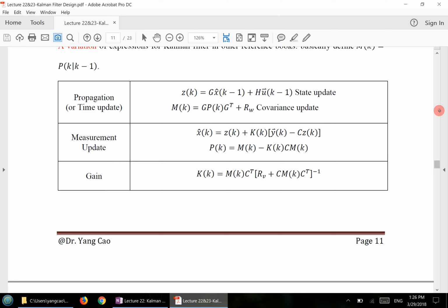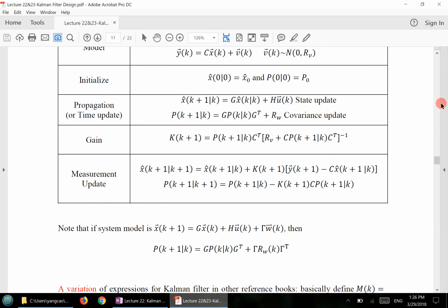So now you come to the Kalman filter design here. You have a gain here, and you have a difference: this is the sensor output minus that Kalman filter estimation output here. So basically, if you're confident that your sensor is generating a clean, good signal, then you must also be confident to do what? I can apply a relatively bigger gain K here, right?